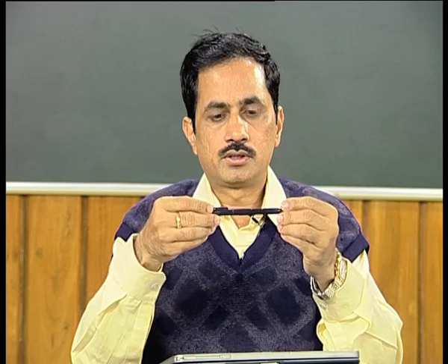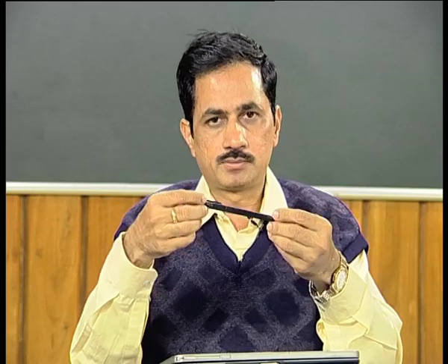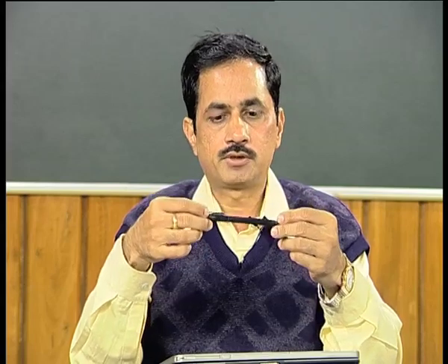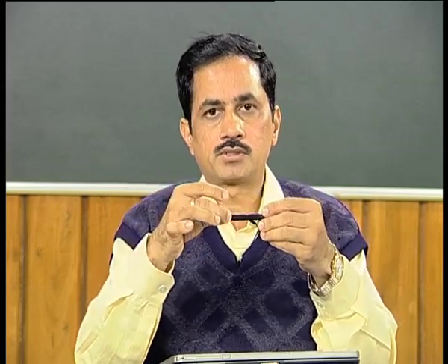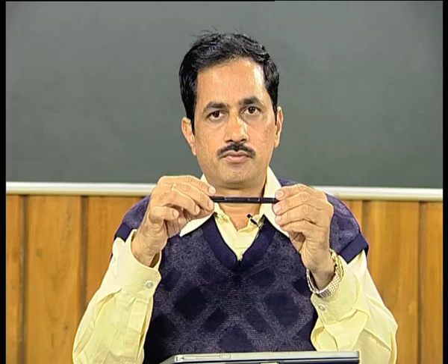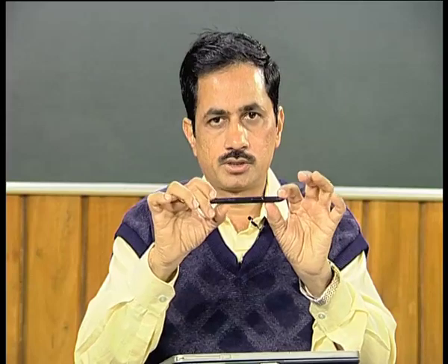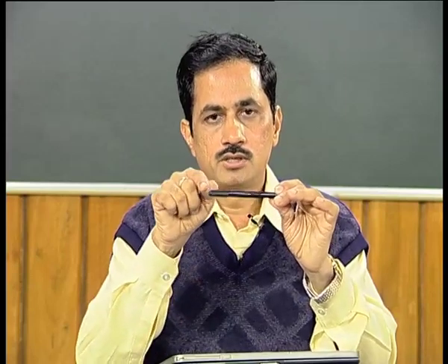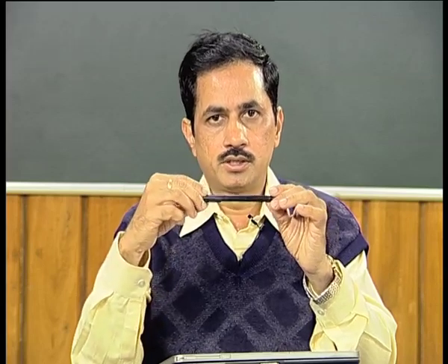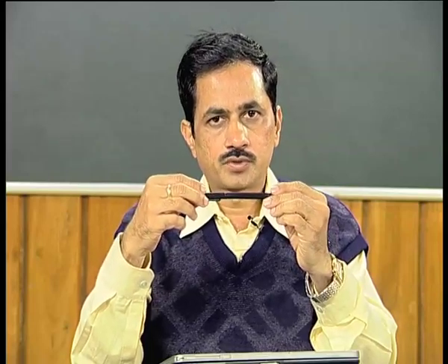Whatever the displacements of the bearing are, those will be given to the two ends of the shaft when we consider the shaft as rigid. Because of the displacements from the bearing, the disc will have some displacement. In the second step we will consider the bearing as rigid, and because the shaft is also flexible, it will deform in some shape. Because of that, what is the displacement of the disc? These two displacements we need to add vectorially.